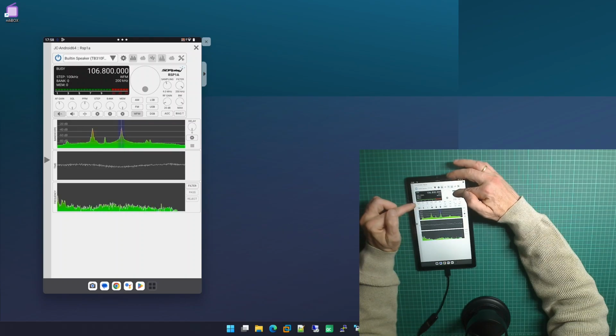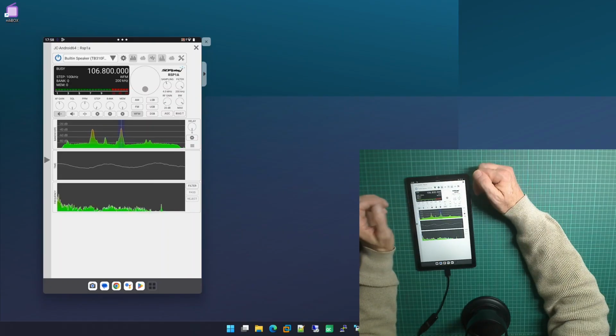When we go very high in sampling frequency, then it starts to fail. You may even have a crash of the application because it cannot handle that frequency. I recommend something like 4 megahertz, but it depends very much on what kind of hardware we are using.